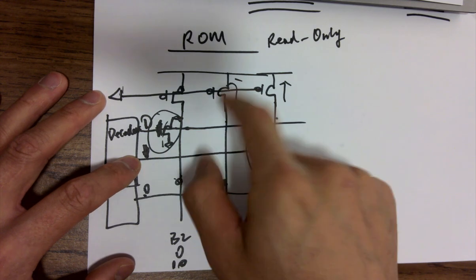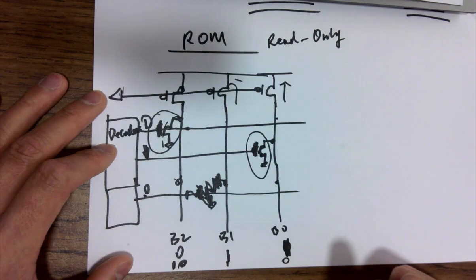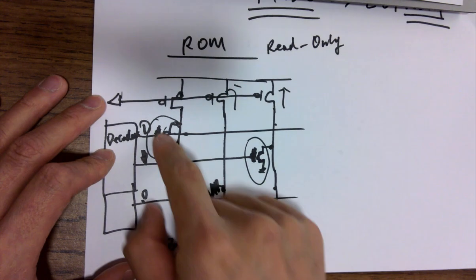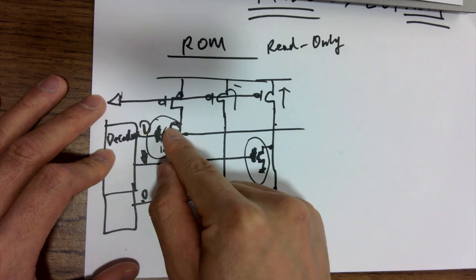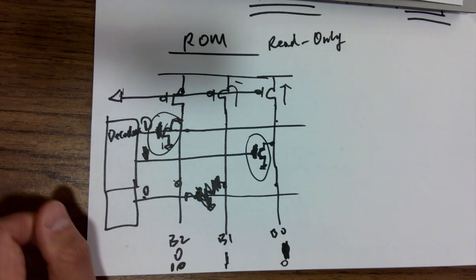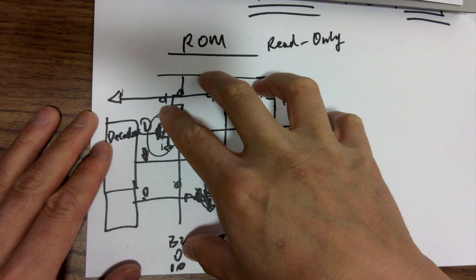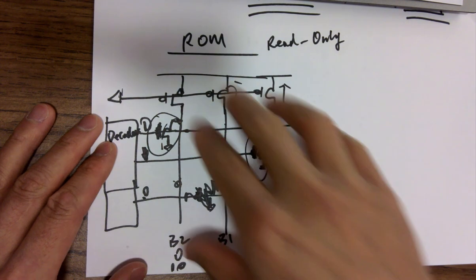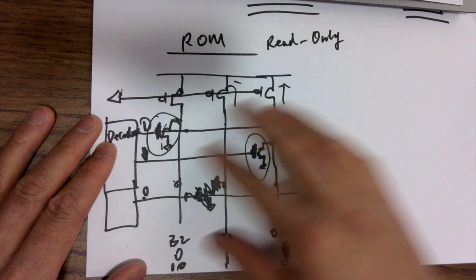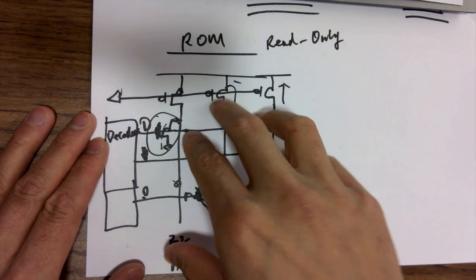Can I write to this memory? No. No, it's read only. You cannot write to it. These are already designed. It's placed. It's physically connected. So this could be used as a bootloader circuit for the microcontroller, and whenever the microcontroller is getting powered up, this data will be automatically read into the CPU as preloading some kind of code or data into it to start things up. It's quite useful, but it's read-only. Cannot change. Can never change it.